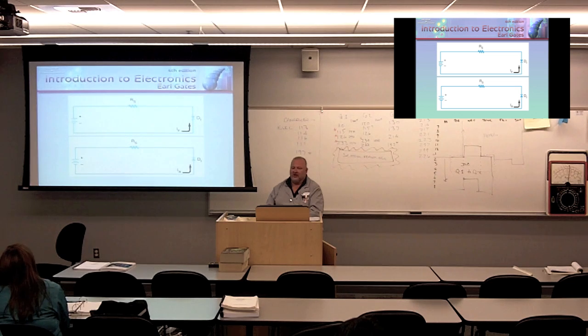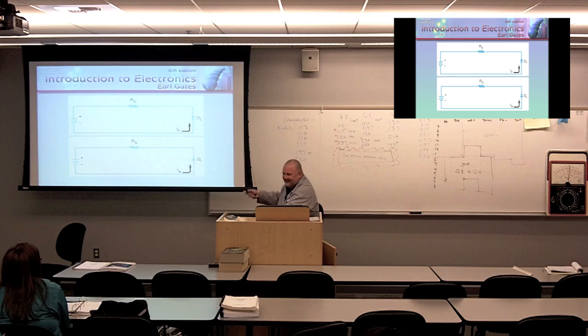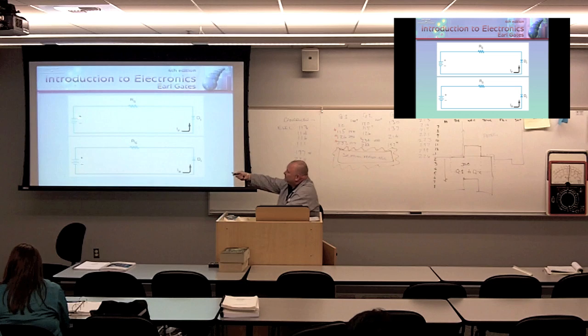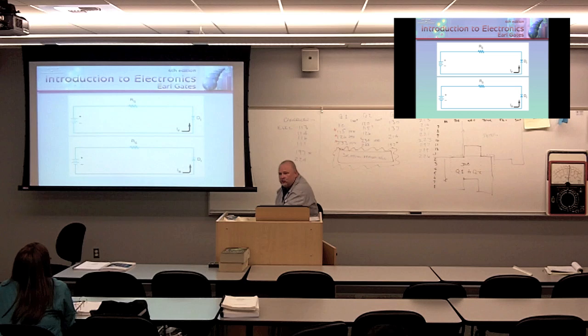It's a simple series circuit. Another term for a series circuit is a voltage divider. The big thing to look at is we have the negative connected to the cathode and the positive connected to the anode, so we're doing what to this? Forward biasing it. I gave you a hint by showing the I sub F right here, forward bias. So current is going to flow through and create a 0.7 volt voltage drop here. So 10 volts minus 0.7 gives us 9.3 across that resistor. Make sense?